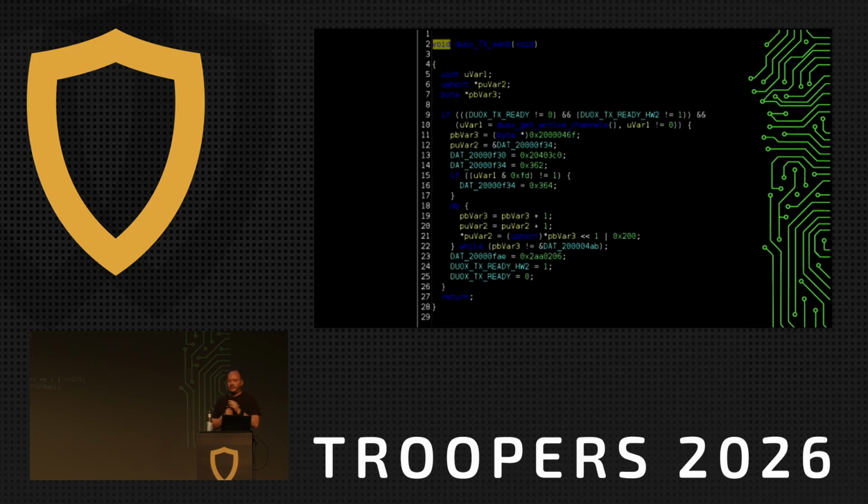Looking at DUOX send, it basically copies the data to the right space in memory depending on the channel, right? There are these 4 channels, well, 2 channels for outgoing that you can use. And on the bottom, line 24, it says DUOX ready hardware 2 equals 1. That's like the next step of processing. So this function, all it does from the beginning to the end, is just copy the data. No processing, it doesn't change the data at all, right?